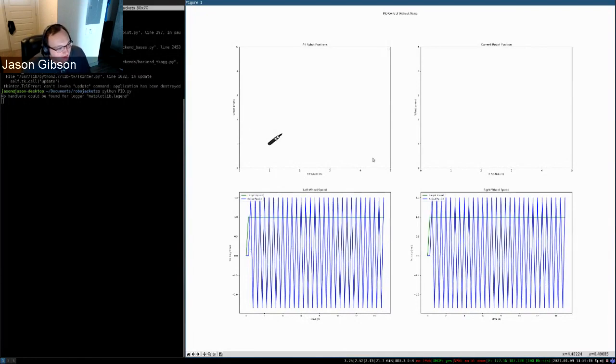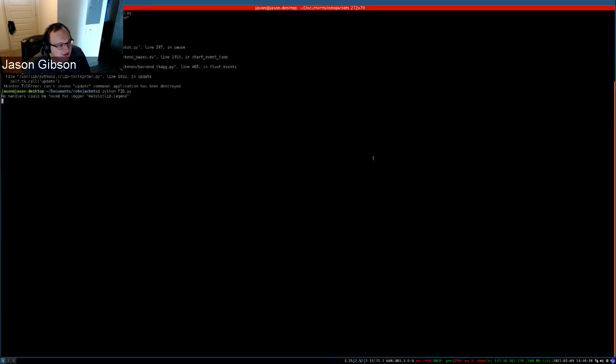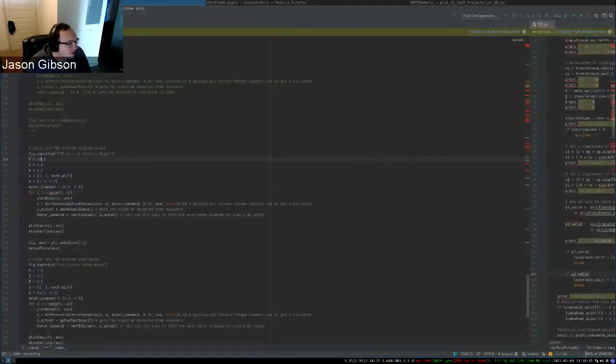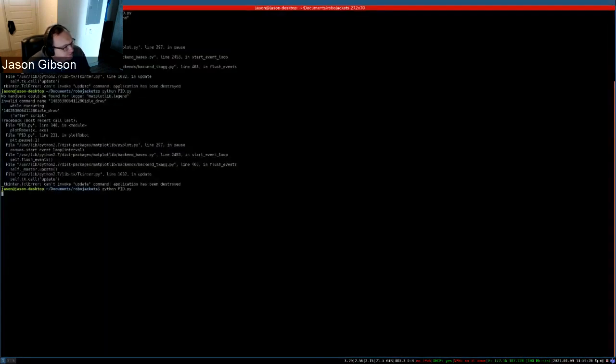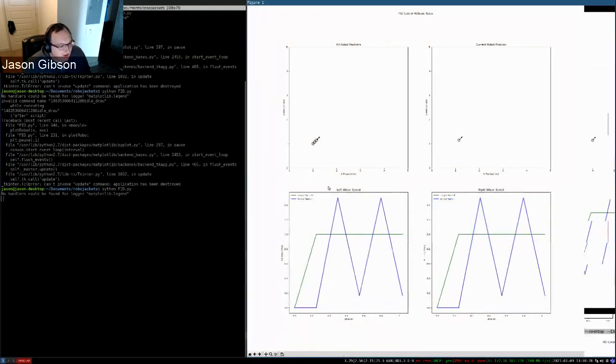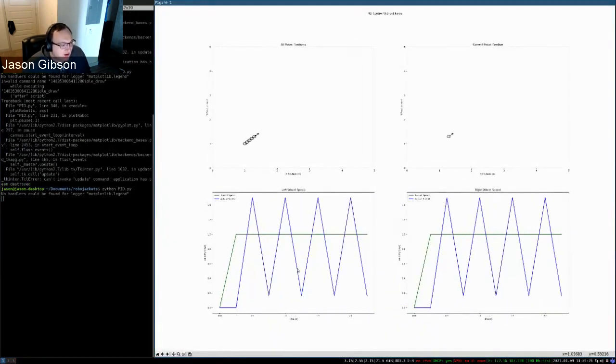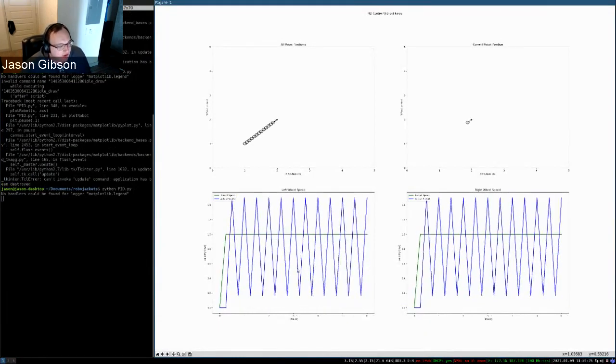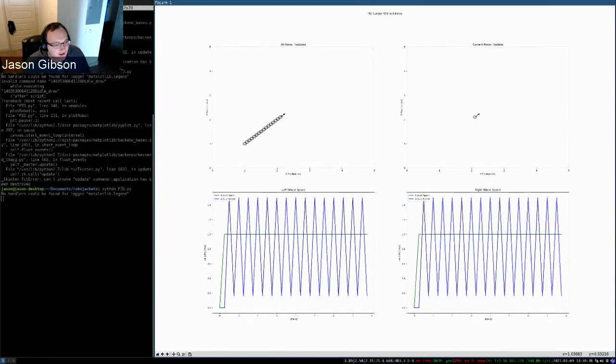So it does this, and this means your P is too high. Do you ever see something that looks like that on your velocity curves? Your P is way too high. So let's set something around like 8. So now if we look at a P of 8, you can kind of see the velocities down here. We're oscillating, but I think we reached our set point pretty quickly. And we're also not oscillating too bad,